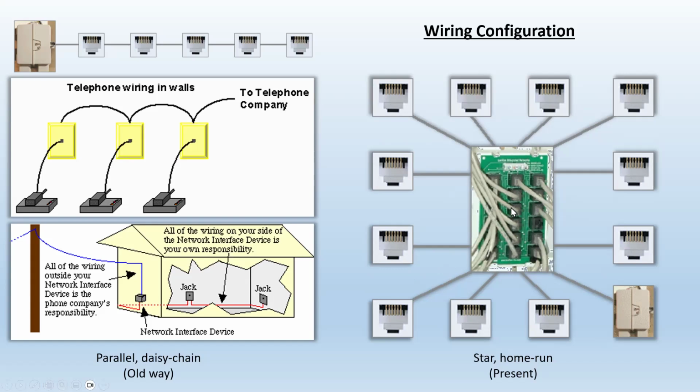And if you use the Cat5e or Cat6 wire, then that jack can be used as either a phone jack or a data jack, because you already have the data connection wired in T568, not in a USOC configuration. But since you want to use the phone, pair blue, which is pair 1, which is the two middle prongs, is still wired to pair blue.